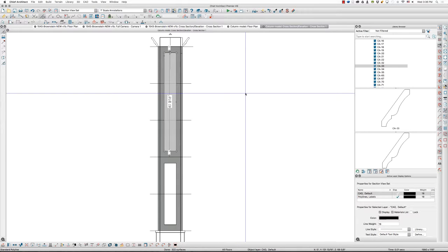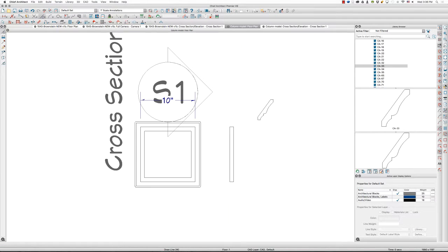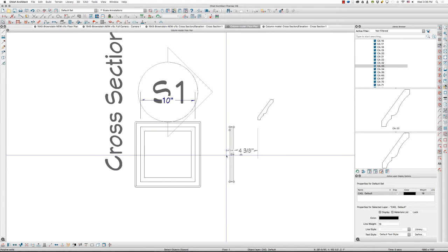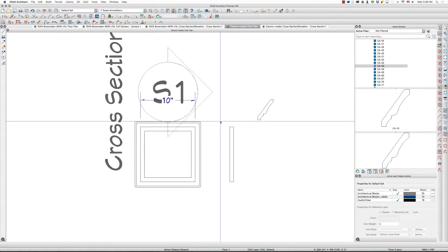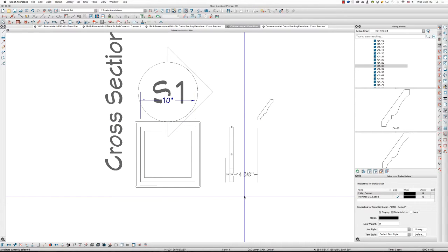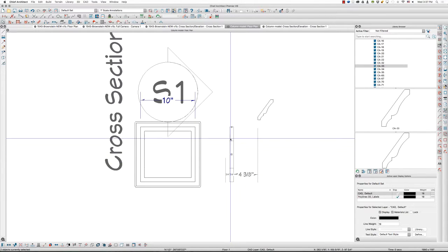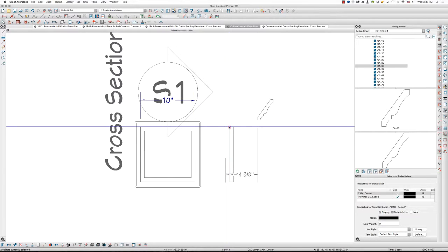Perfect. Now I'm not going to do anything with these polylines just yet because I want to go into plan view, and we see our objects, polyline solids here, and I want these four pieces, actually there's two polyline solids and two polyline solids that have been turned into holes, and I want to move this back. So I'm going to point to point move, X on my keyboard, from this corner to this corner.